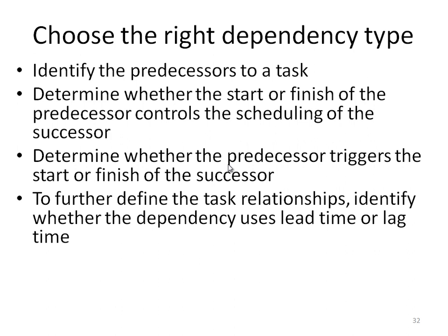The finish to start dependency between the paint first coat task and the paint second coat task includes a 4-hour lag. So although the first task finished, the second task cannot be started until 4 hours later, so we have a lag time of 4 hours.